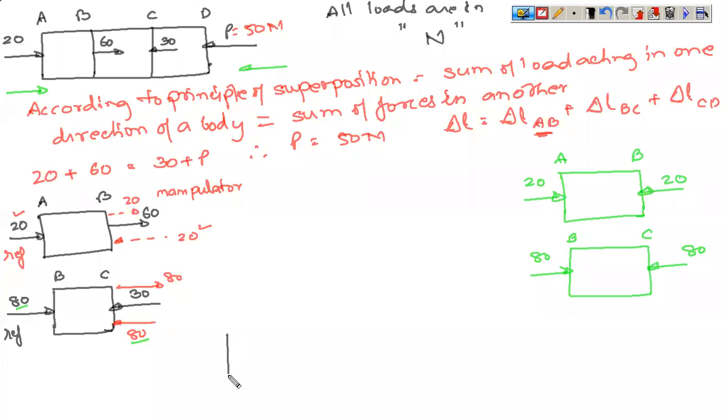So that means if you draw the third section, CD, it is 30 here, 80 here. That means it is 50 here. And on the other side, you have 50. So the last segment is automatically balanced. If this is not automatically balanced, that means somewhere you have gone wrong. Okay. So this is the entire balance structure following the principle of superposition for this diagram.